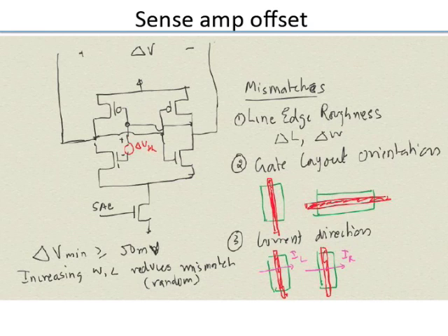So actually on the orientation of these transistors, whether the variation of voltages is totally random, or we can prejudge that one of the orientations is having higher or the other is lower? Yes, that is a good question. This is actually a systematic variation. You can predict, but you need to be able to go all the way to the processing and be able to understand how the processing is happening and so on. So then you can predict.